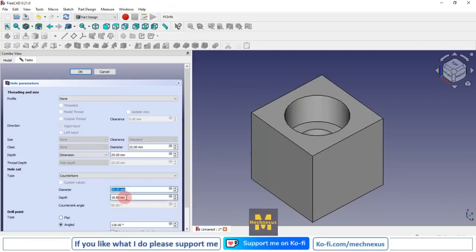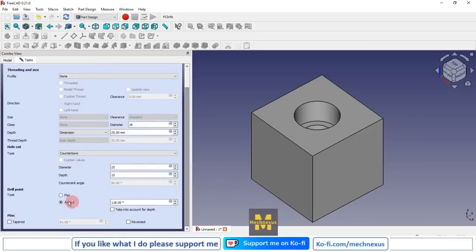Let me make the small diameter 18 mm, and this big diameter I make 25, and depth I give 15 mm. So here is a counterbore, and here it is the same. We can change the angle or keep it flat or give the taper. And now we will close it.